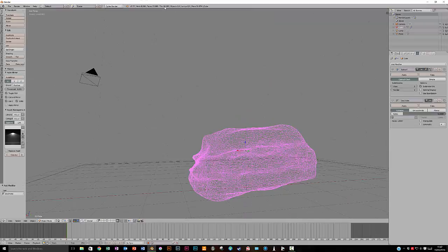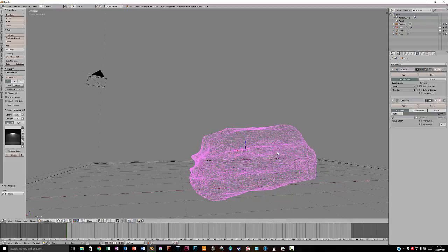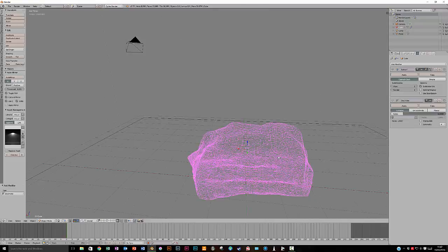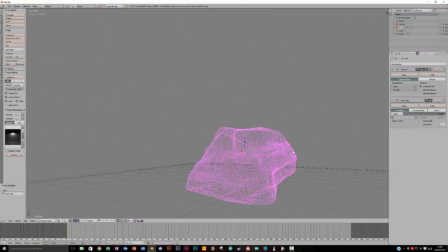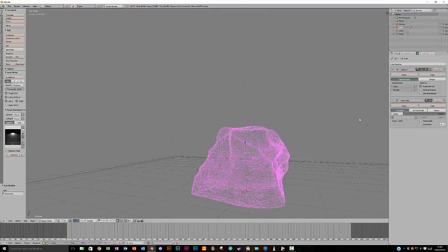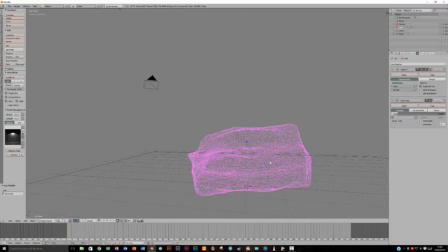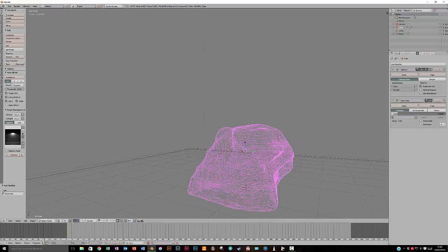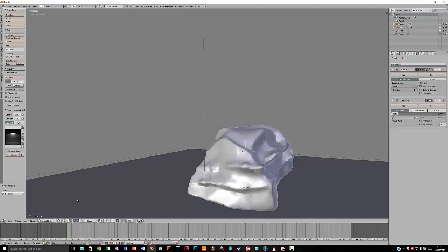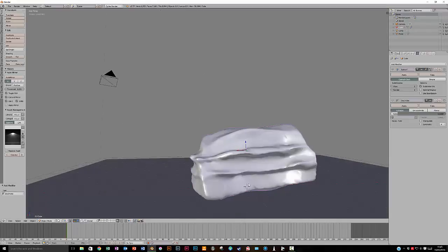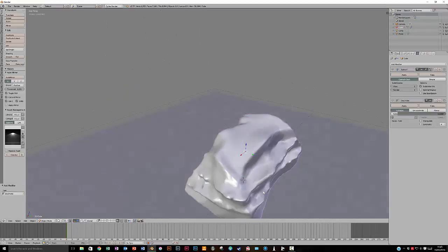We're now down to 16,000, so we've got down from 80,000 polygons to 16,000, and still kept the sculpted shape of the rock that we want. Just going to try one more, 0.1. Yeah, that still looks good. And we're now at 10% of the polygons.